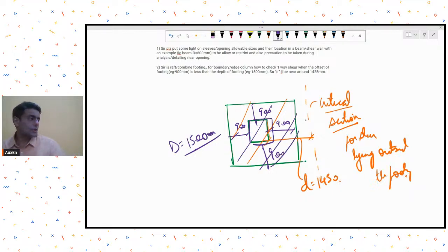Because most of the shear forces will directly travel to the column by the strut action, you could say. So the effect of shear is anyway not being felt in this d distance. Up till a d distance, my column is over there to take any kind of force, and it will be resisting all those shear forces as a matter of the strut action between footing and column.